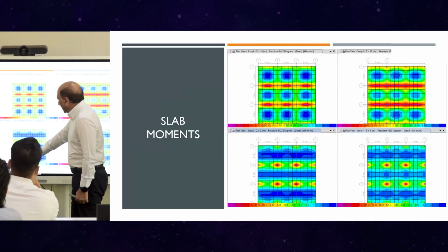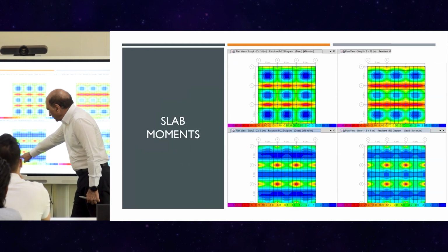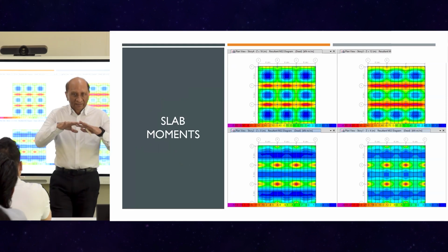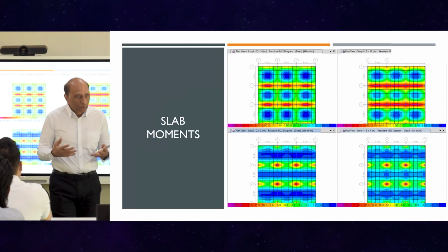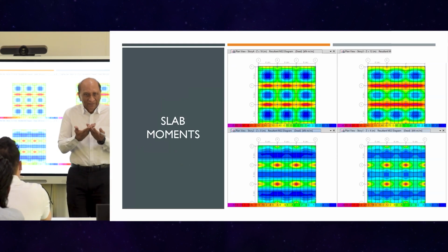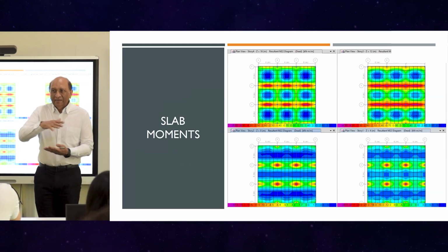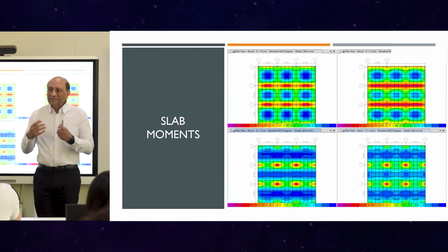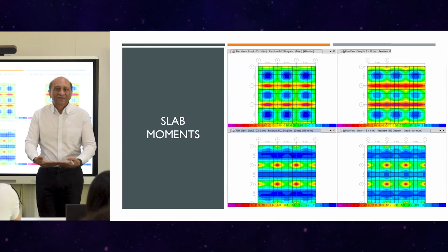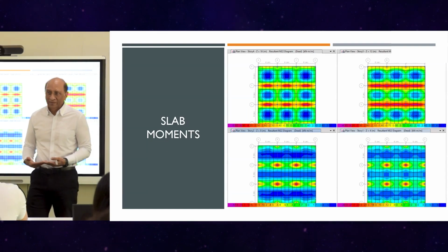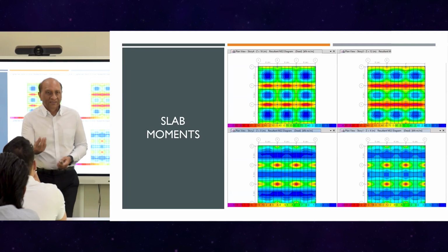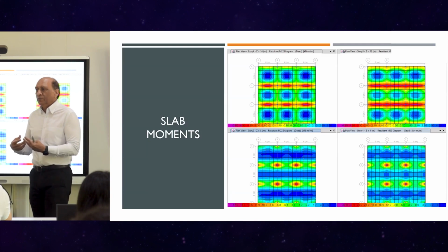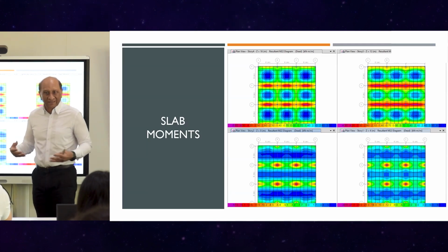So the column is here where you can see red. Red means it's a negative moment in the slab, and green or blue means it's a positive moment. Positive moment means that the slab is bending like this. Negative moment is that it's over the column, the curvature is reversed. So if it's a negative moment, that means there is a support underneath that. That's why there is a negative moment. So whenever there's a red color, it indicates that there is a support underneath that. And whenever there is a blue color, that means the deflection is maximum, the moment is maximum, there's nothing there.